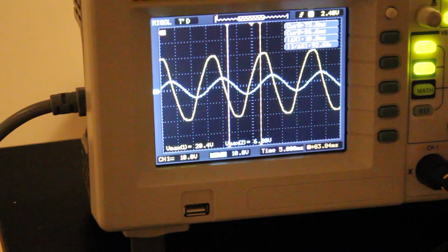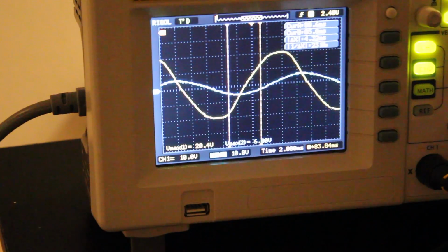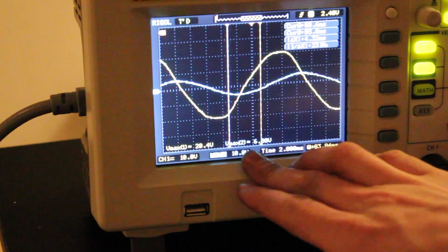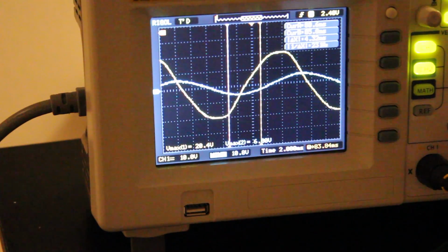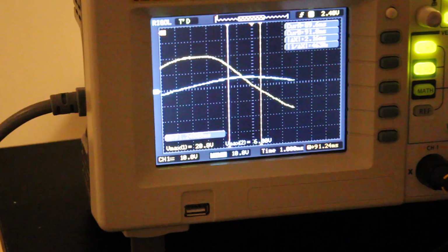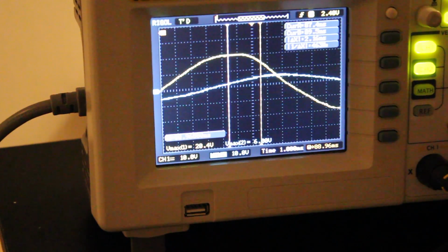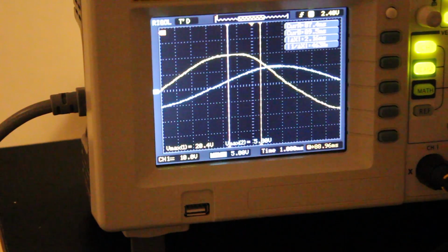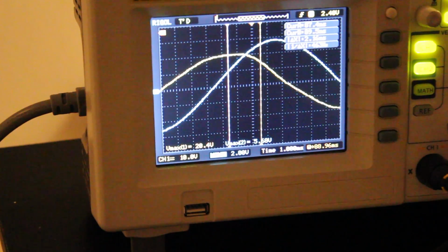Huge difference, right? So now our peak is only, let me zoom in a little bit here. Our peak is only about 6 volts. Okay, so our total gain is, remember, V out over V in. So our 6 over 20 is about 0.3-ish. I could actually probably get that a little bit better on here. So it's actually about 5.68. Just want to get a little bit more accurate, over 20. That's 0.284 is that gain.